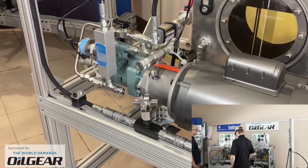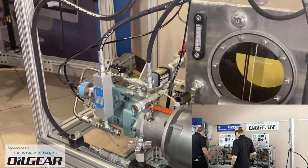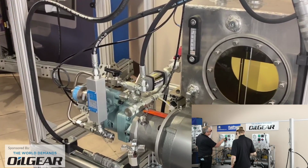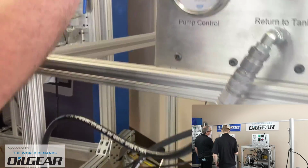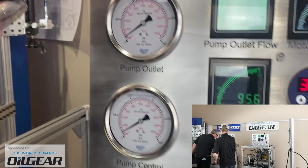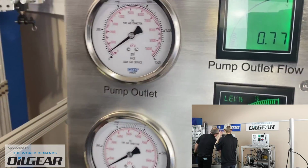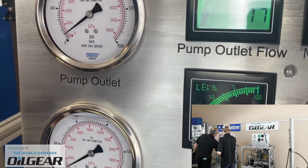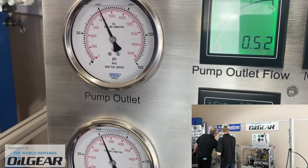So right now we don't know what our maximum system pressure would be, because we've got a nice easy flow path, and our system pressure is certainly quite low, well under 100 psi. So let's find out, see where we are by very slowly closing off. The flow rate will drop and the pressure will come up.